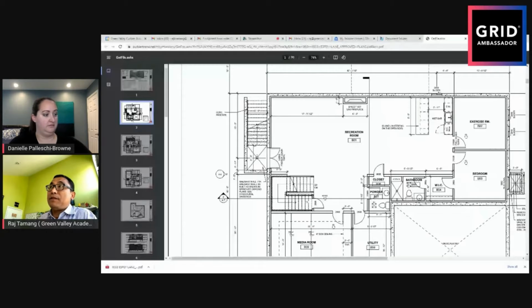Now in this case, I know this is a buried basement, a fully buried basement. If you go to the grading plan, you will see the elevations of the basement, the elevation of the outside grade, and the first floor. You need to know that before you start working on the drawing, because as an architect or designer, you need to know if the house will be fully buried, a walkout basement, or semi-walkout. All that needs to be known when you design the house. It means you have to coordinate with the civil engineer hand in hand, side by side.